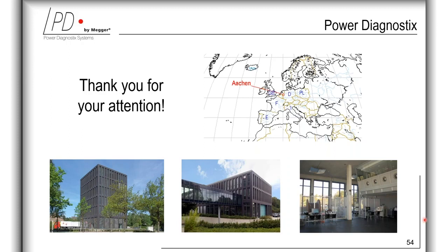So to get these free electrons, we need either a material providing these free electrons, or we need ionization. That means a photon from the cosmic radiation hits a local gas molecule and produces free electrons, which can be accelerated in an electrical field and then cause the PD pulse.